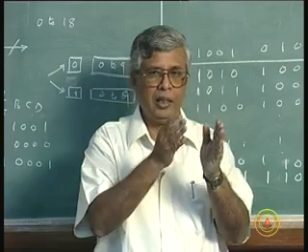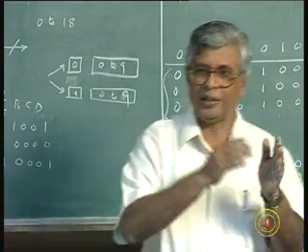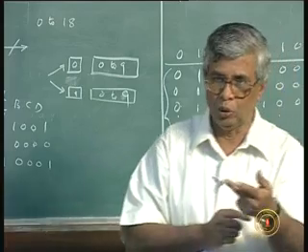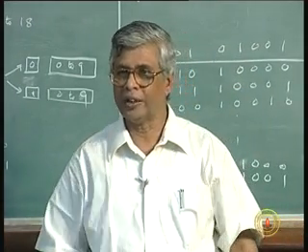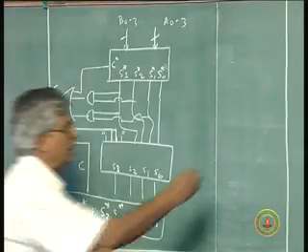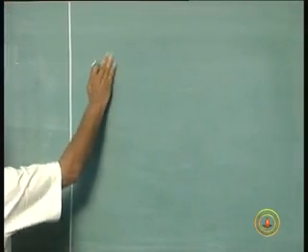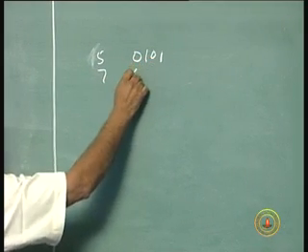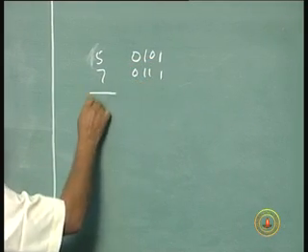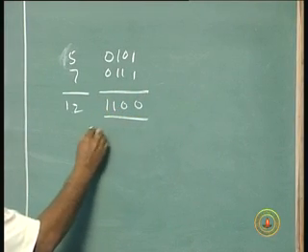That last one is the 16. If you remove that 16, the remaining is 2, and the 2 will be converted and will drive the 7 segment display. So, 5 and 7 give 12, no problem, but I do not want this. So, add 6 to that.